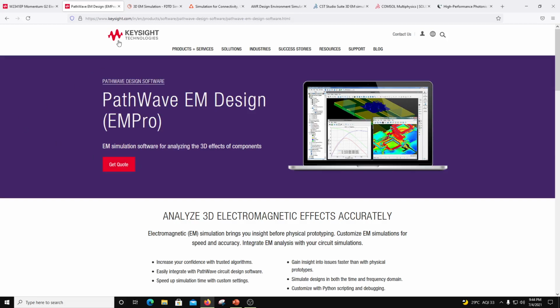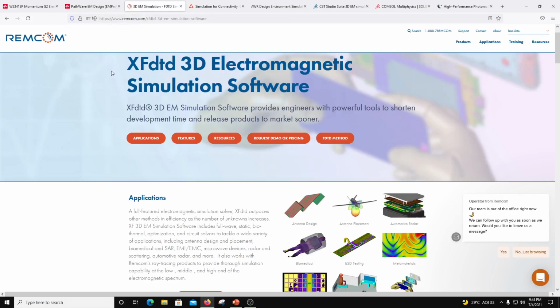Now how do these two, FDTD and FEM, deal with fields which are far away? What they do is you box the object under consideration, where you calculate the currents and voltages and the related fields E and H, right? You do it in a smaller geometry, but then you put it in a box, and once you collect all the fields at the edges of the box, you can apply certain transformations to transform the near field to the far field. So that's how antennas are simulated.